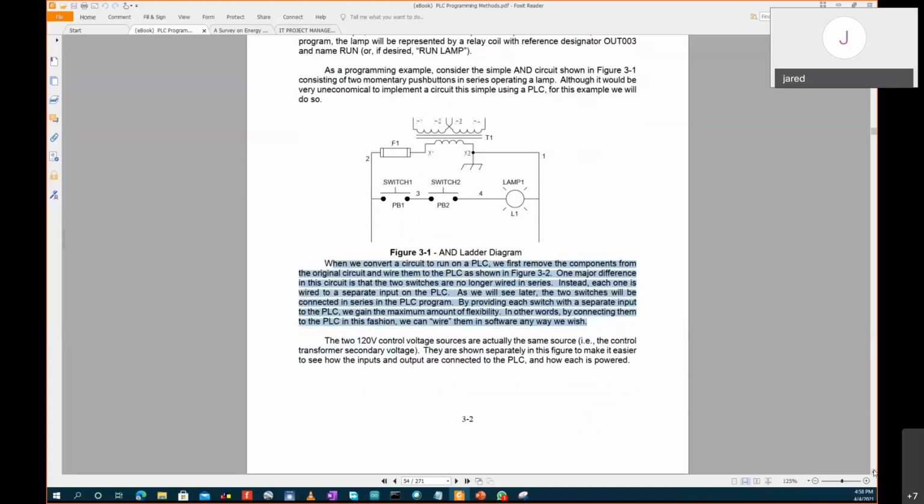So say this one maybe is going to be your input 1 and common, because there are two contacts. It's the same way you do for Arduino. You take 12 volts and put it on the input, or you take 0 volts and put it on the input. So you have two references. One goes to the digital input, another one goes to the common, which is your common terminal. That is like a reference terminal.